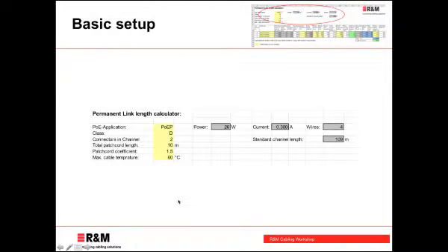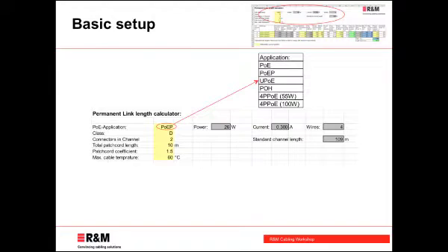Here we actually define the application that we want to run, with obviously the most important one, the application PoE to PoE plus or 4P PoE. So we have two different levels for 4 PoE, with the minimum level according to the standard and the most likely one that we would end up with, 100 watts.